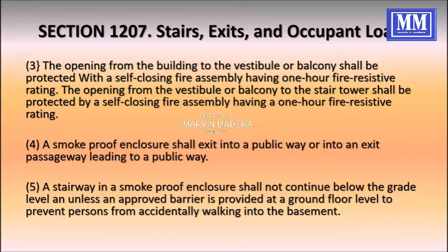A stairway in a smoke-proof enclosure shall not continue below the grade level unless an approved barrier is provided at the ground floor level to prevent persons from accidentally walking into the basement.